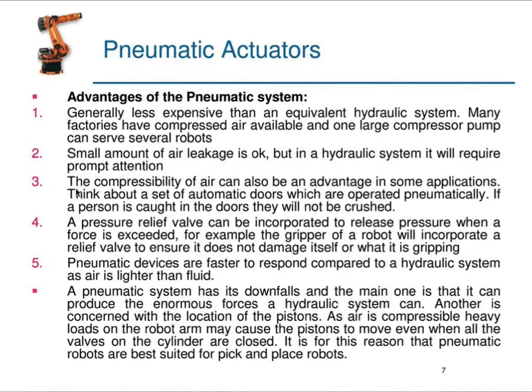And the third point in the pneumatic system, the compressibility of air can also be an advantage in some applications. Think about a set of automatic doors which are operated pneumatically. If a person is caught in the doors, they will not be crushed.